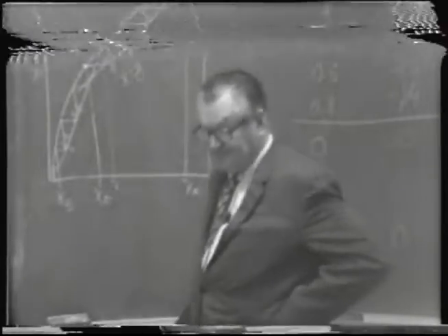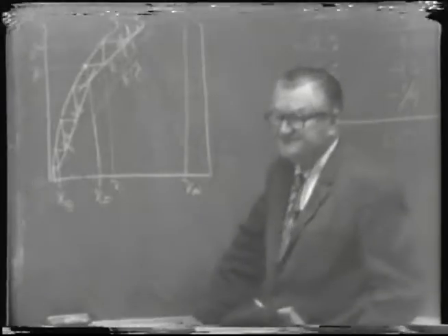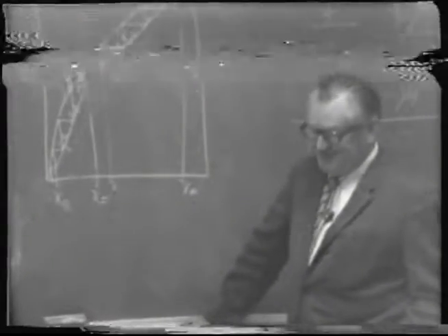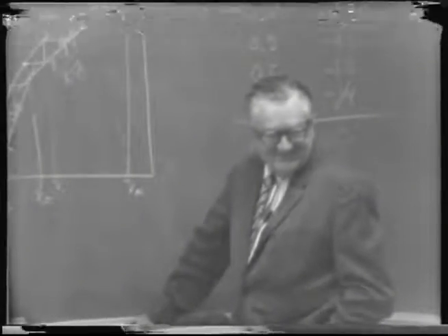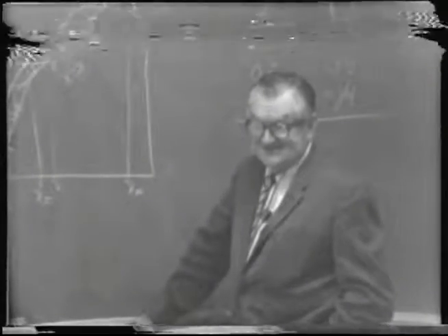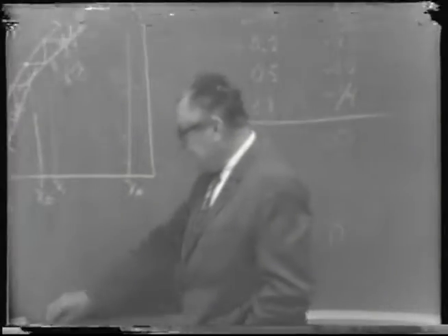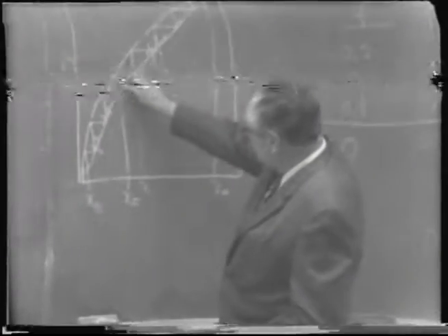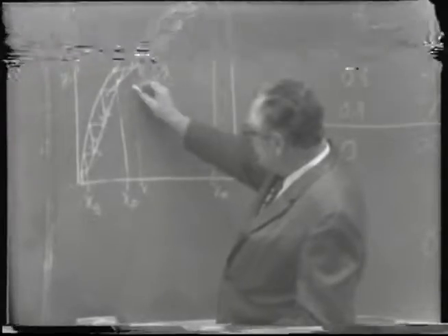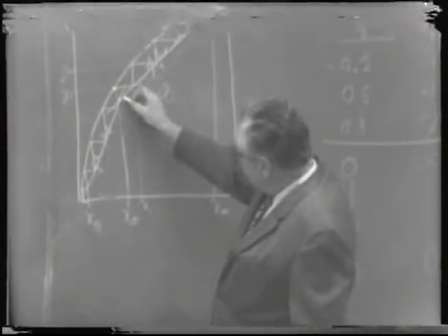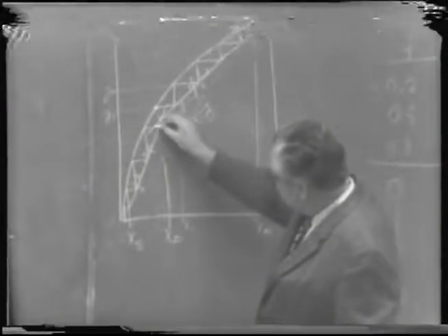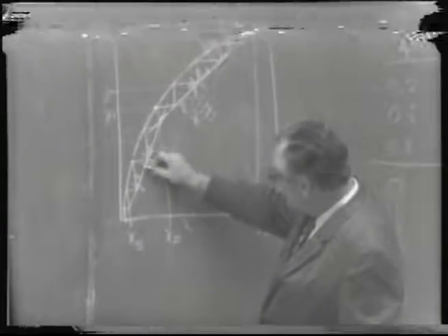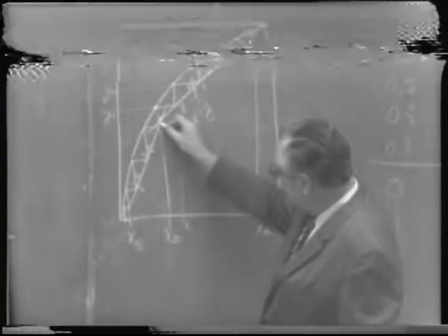What's the point where the two operating lines meet? Well, it's simply called the point of intersection of the two operating lines. What do you get from that? It means that to the left of the point of intersection, you take the steps between the curve and this operating line, not the projection of that one or the projection of this one.